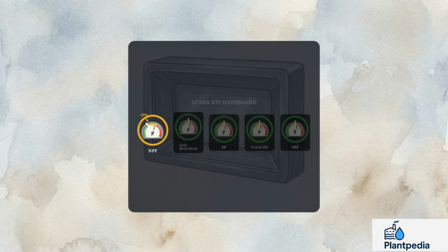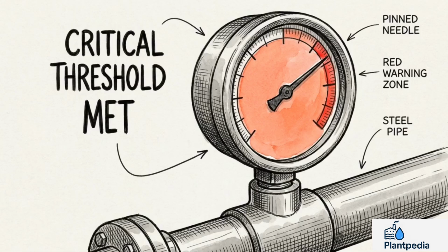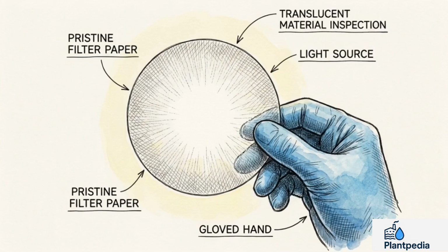The second metric is salt rejection. A sharp drop here confirms that physical, structural damage to the membrane has already occurred. The third metric is differential pressure. A rise greater than 15% confirms severe, flow-restricting fouling is blocking the feed channels. Metric 4 is feed SDI. It must strictly remain below 3 at all times to guarantee your pretreatment integrity.